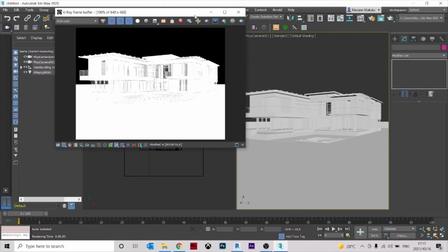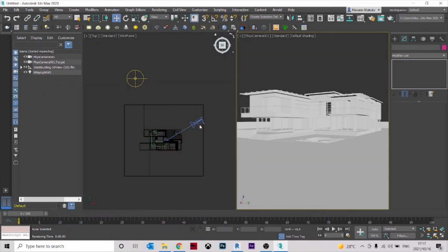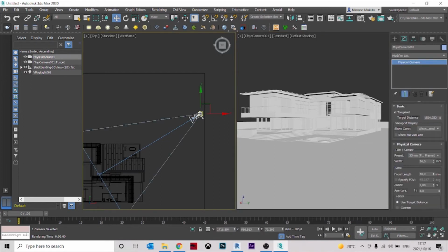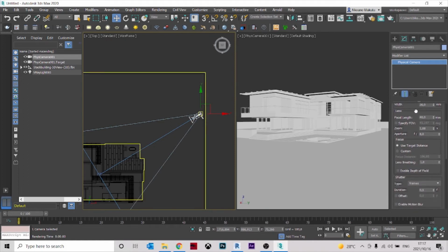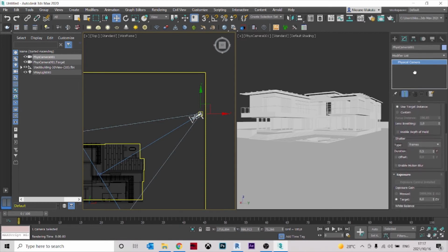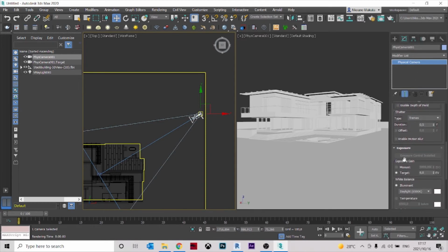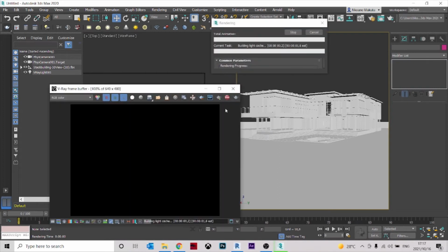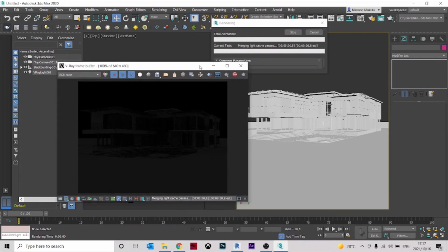So what I'm gonna do is I'm gonna remove this, and I'm going to go to the camera and change the exposure light of the camera, because the camera itself has an exposure. We can change the exposure here by typing. We can start with 16 for example, and without changing too many settings, we check again what Vray is giving us. Again, it's too dark.